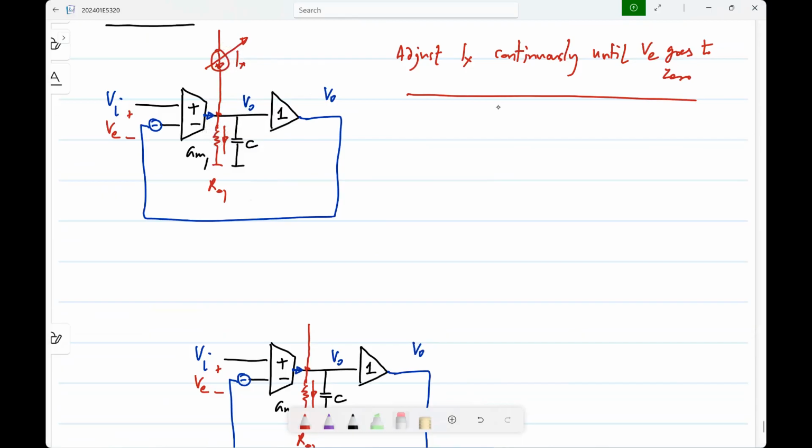It's not as though when this is equal to that, this voltage stops changing. Even if this voltage was, let's say, 10% less than what it was supposed to be, if you go on injecting the current, it will go on increasing. That's all. So you can't find out here. What you want is for the error current coming out of GM to be equal to 0.